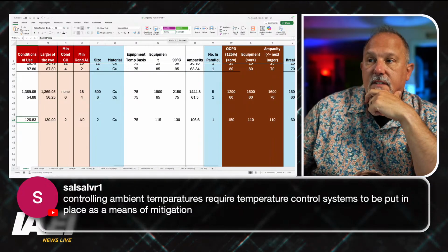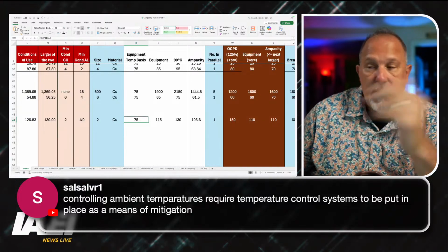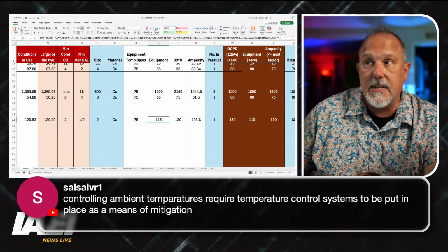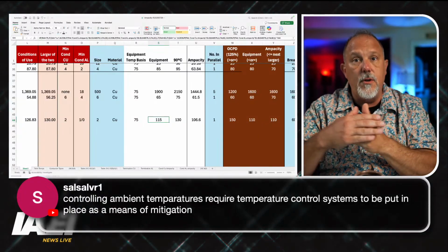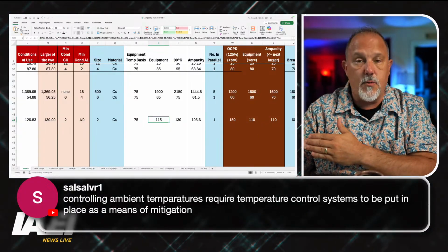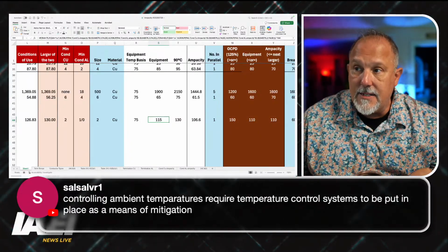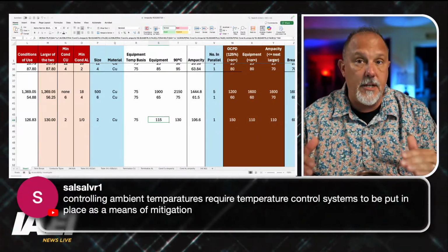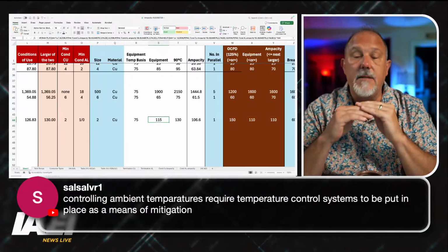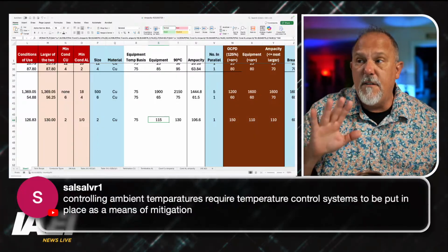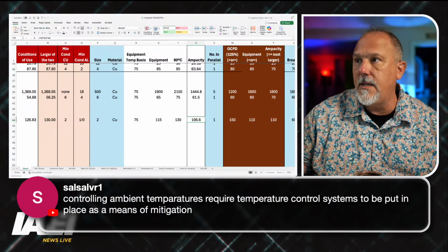The equipment, if I'm in 75 degree C equipment on both ends, tells me I can't exceed 115 amps for a number 2. If I land a number 2 in a piece of equipment that is 75 degrees C, and that's my weakest link, I can't exceed 115 amps through that termination. That has nothing to do with the ampacity of the conductor, but it is a limitation for the circuit. So what I'm going to focus on right now is the ampacity is 126.